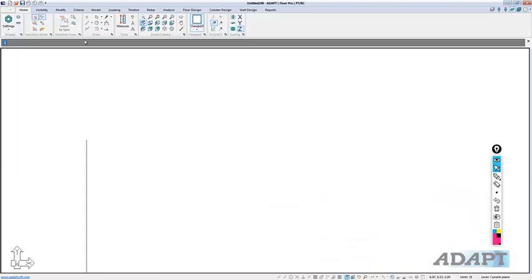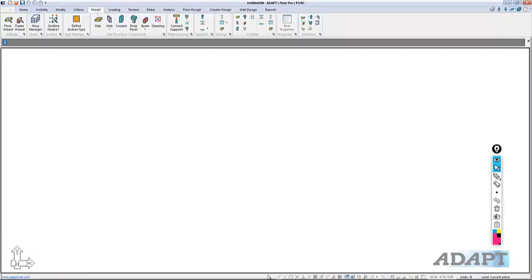The first thing we want to do is go to Model, and you'll notice at the bottom, this is the user bar at the middle bottom of the screen. We have snap tools. These are docked at this location. They cannot be moved from this location, so you may be referring to this set of tools quite often in the modeling process. And the reason we would model something natively might be for lack of a CAD file. It might just be a very simple model we're trying to set up, or it might be modifications to an existing model.